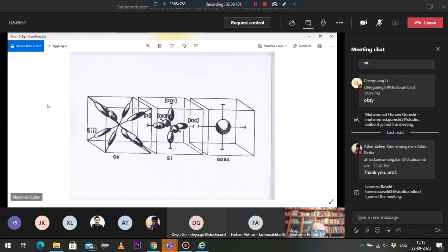By the way, also the two branches of the valence band in these semiconductors have a spherical symmetry. When you consider silicon, you have 6 minima symmetrically placed with respect to the origin in the 3 directions of the K vector, 0, 0, 1, 1, 0, 0, 0, 1, 0. And the surfaces of equal energy are ellipsoids of revolution. So those forms that you can see in the figure are ellipsoids.